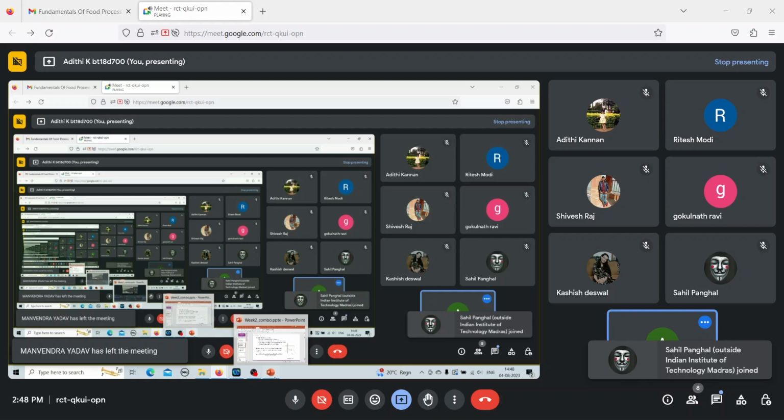So now we know that for an elastic material, stress is proportional to the strain, which is this. For a viscous material, stress is proportional to the rate of strain, which is this. So if I am giving a sinusoidal strain to an elastic material, my stress equation will look exactly the same way. There is no phase shift here. There is no omega t plus something. It is basically omega t plus 0 degrees. Is this part clear? So your elastic material will have a 0 degree phase shift.